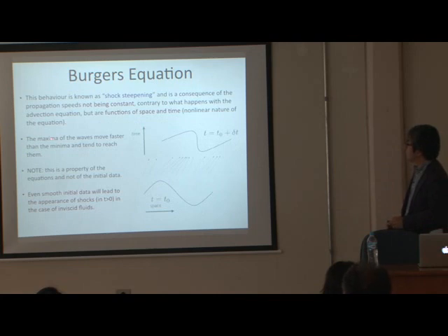The maxima of the waves move faster than the minima and tend to reach them. This arises from the equation itself, not from the initial data. So even smooth initial data will lead to a shock after some time, in the case of the inviscid fluid.